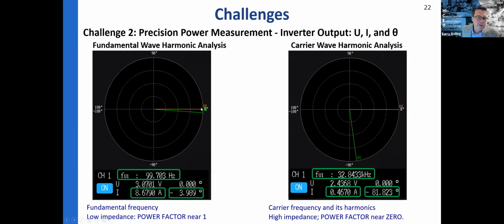While the voltage waveform is easy to measure, introducing the magnetics and the electronics to measure that current, you're not going to be able to use a shunt at higher frequencies. So don't think that. You're going to have to use a transducer, and you're going to introduce a small phase shift. It's inevitable. So just imagine that over here at 30 kilohertz, this angle is large. And you're probably thinking, well, the angle between the two is already large. What's a small phase shift error? Well, it doesn't really work that way. Even though the phase angle here is fairly large, and 2 or 3 degrees would be insignificant compared to that angle, the next slide will show why.